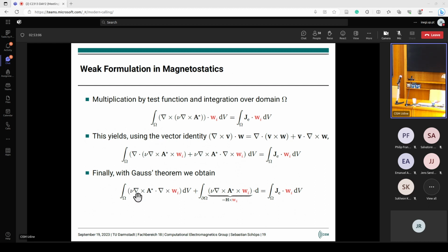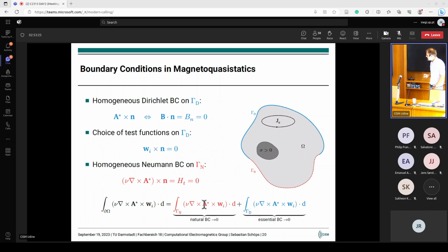So here again, it may look somewhat familiar to you. If you know Laplace's equation, this may be the gradient of test functions, the gradient of your solution, the material parameter, and then we have boundary conditions and the load vector. Okay. So defining the boundary conditions, let's make our life simple. We assume that they go to 0. So we have 0 Dirichlet conditions, for example.